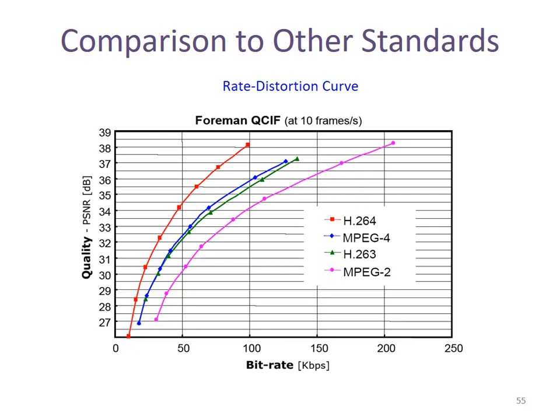The first thing is you can draw a vertical line here to compare, at the same bit rate, which quality is better. If we draw one line here, you can see for H.264, the PSNR is 34, but for MPEG-2, the PSNR is only 30.5 something. So given the same bit rate, the performance of H.264 is better than MPEG-2.